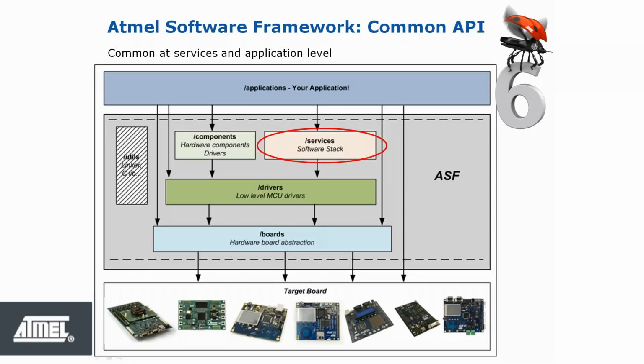Changing from one Atmel platform to another is just a special case of this design process. As you add services or drivers, you will copy the sections of application and configuration code for drivers and services from your existing application to the new one. Think of your existing application as a special example project, which is very close to your application requirements, so needs very little code modification. Even less modification will be required if your application uses ASF Common API.